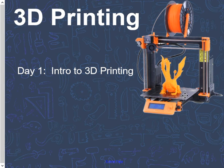The y-axis is actually this print bed. It moves back and forth on rails also. So the extruder can only move left and right, and then the bed moves forward and backward, which gives us the x and y axes. The z-axis is these vertical bars, and the entire x-axis slides up and down the vertical bars as it's printing.